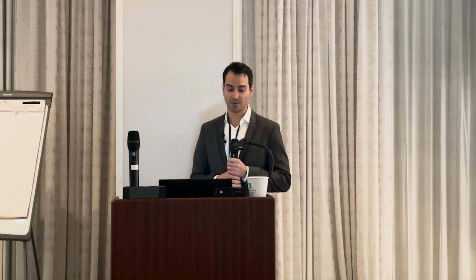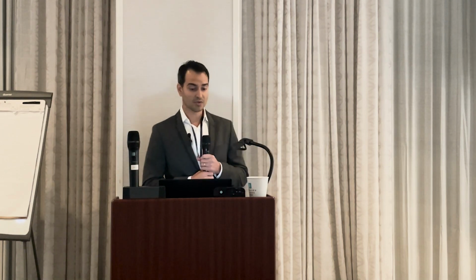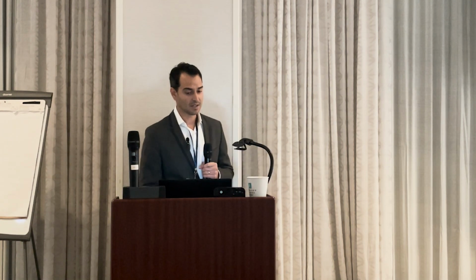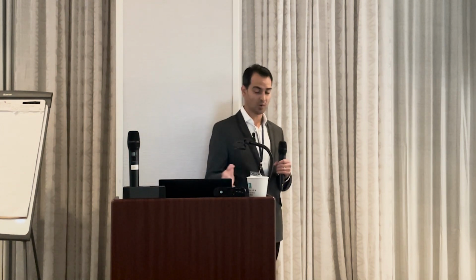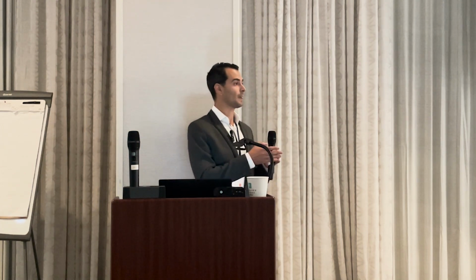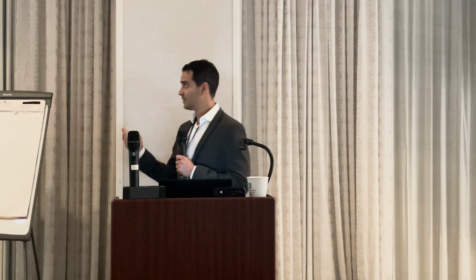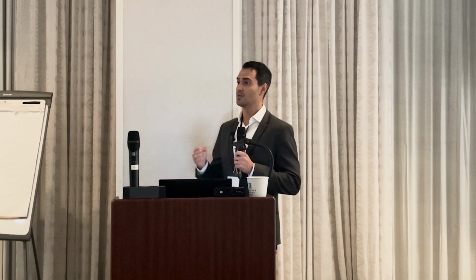So it provides quasi-isotropic properties to this type of glass reinforcement. As you can see, the glass content is between 55 to 60%. It's higher than the chop strand mat and way higher than the surfacing veil. And for that reason, we use this type of laminate just for structural strength and for the structure of the laminate.